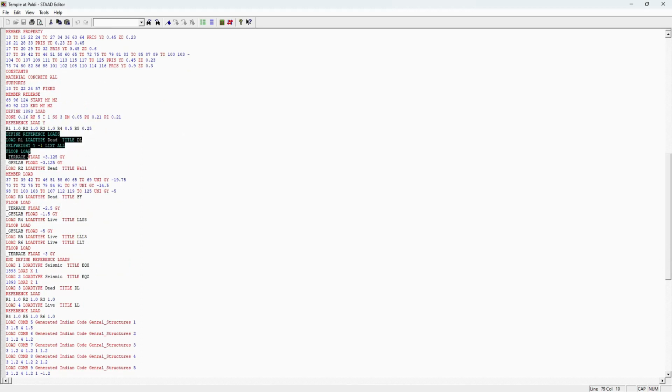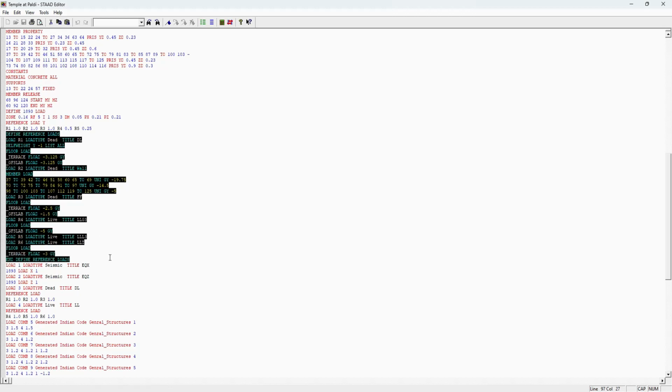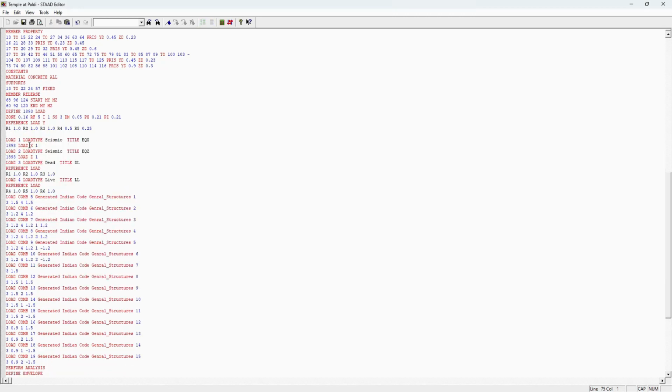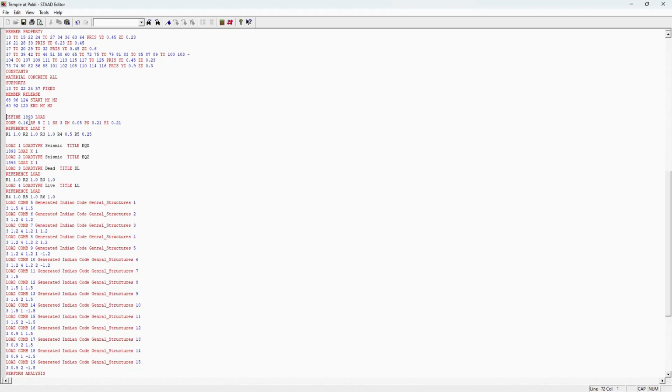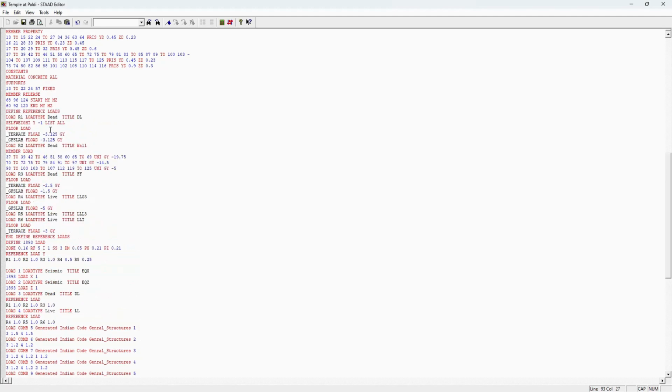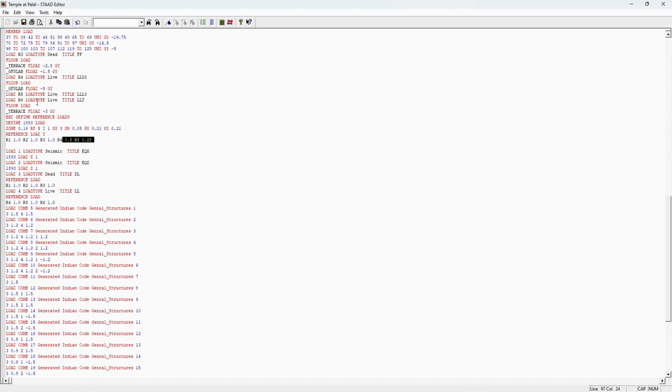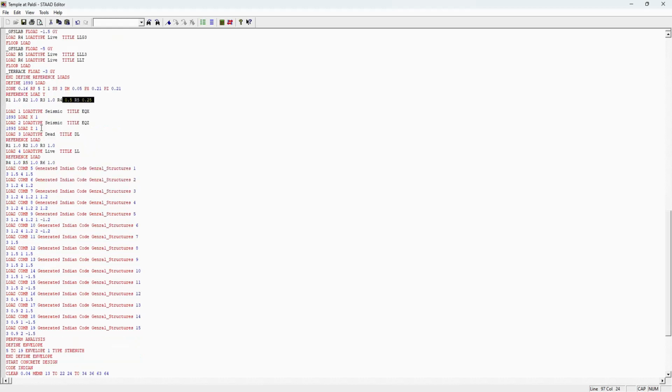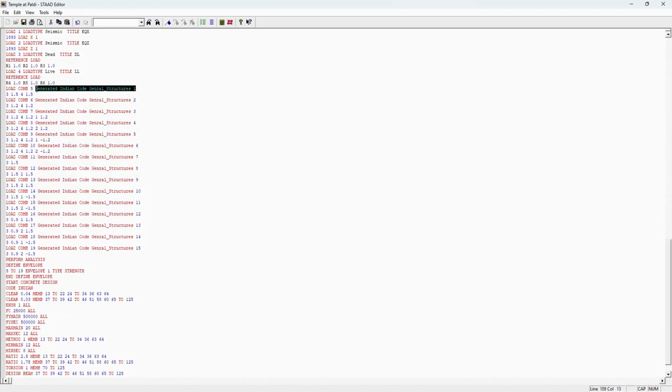and then we have given the reference loads. But as you can see, the reference is being given before the load has been defined. That cannot be possible. So we have to select the definition of a load, the reference load, and cut and paste the same above the seismic definition, so that when it refers, it comes from the above lines and not the below lines. Then we have created the load cases, then combinations. You can remove this and add simple naming so that you can understand. It's 1.5 DL plus LL. This is 1.2 DL plus LL.